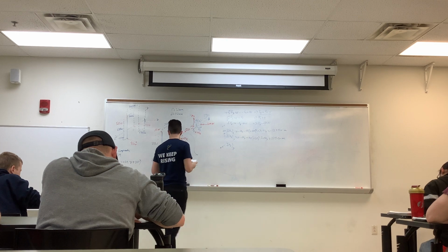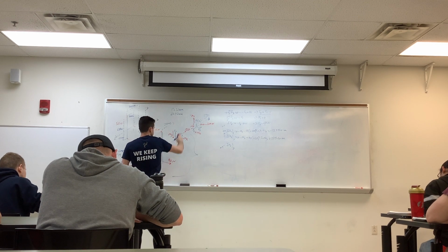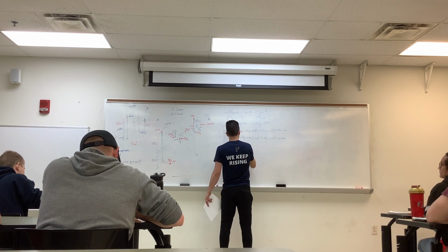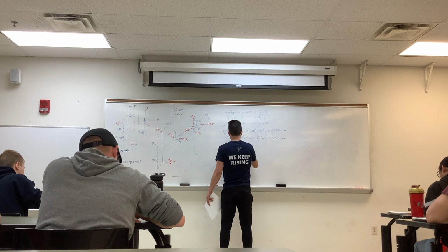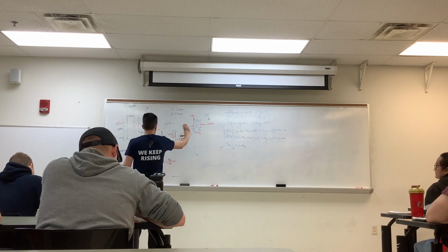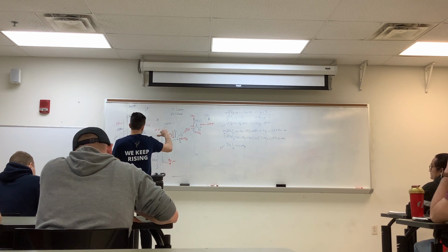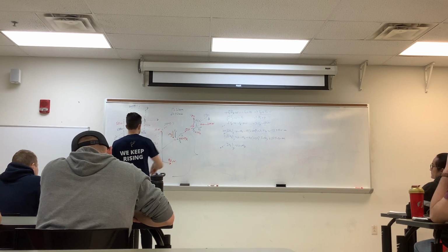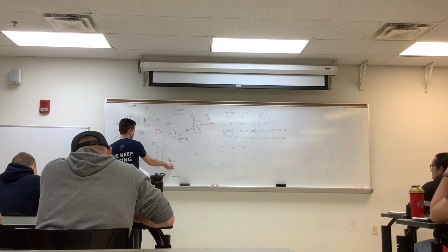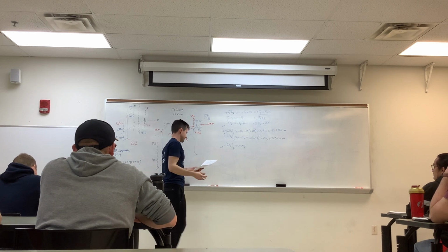And then lastly, we're supposed to do respect to the z-axis. This moment about z is opposing what we assume to be positive when we're doing this equilibrium equation. So negative Mz. Doing the right-hand rule again, putting our thumb along what would be the length of this T section, curling our fingers, what causes it to rotate about it? This 55 newton force is in the plane of it, but this 90 newton force causes moment about it.